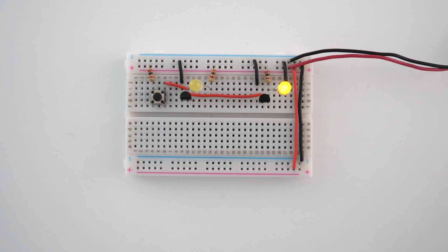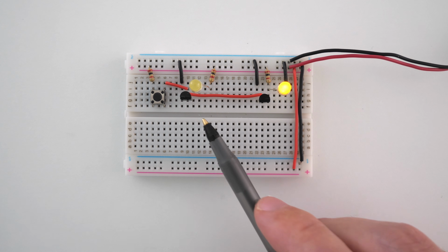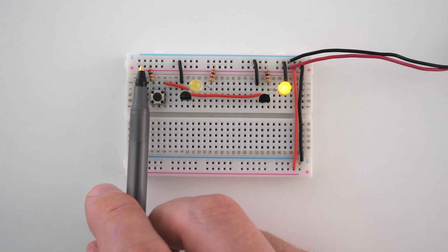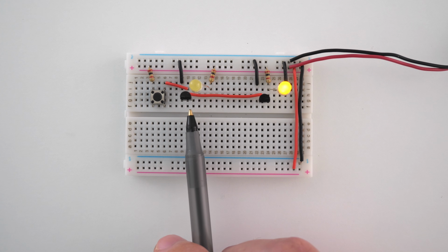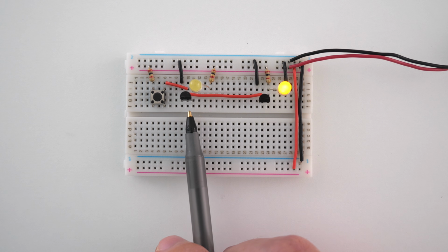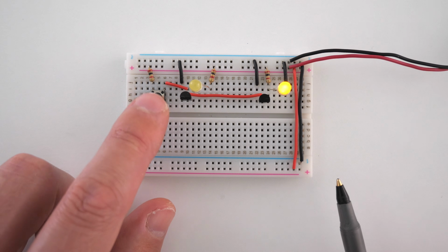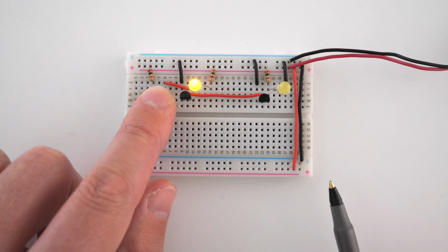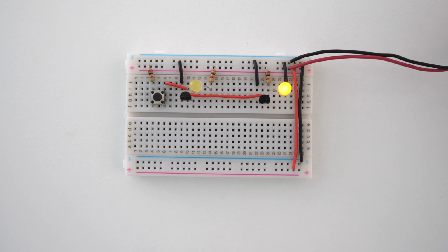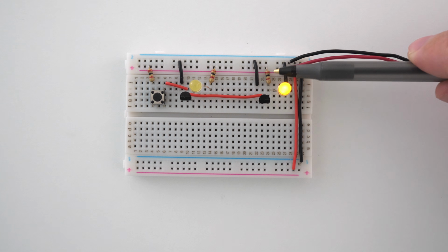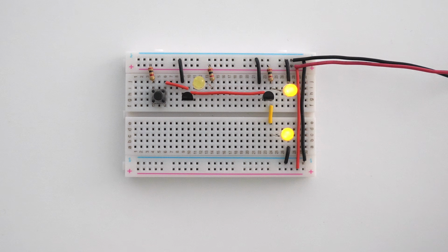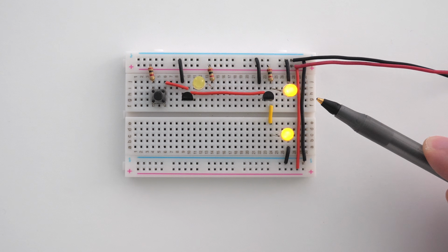This circuit is not any particular logic gate. We have a switch and an inverter, and both of these are hooked up to positive 5 volts by going through the switch and then going into the inputs of the transistor, which is the base of the transistors. And you can see that this is opposite logic. So if we press the button, they do the opposite thing. And you can see how these are wired up differently, where the inverter has a second ground and the switch does not. The main reason I wanted to show you this circuit is to explain how the output is sent.